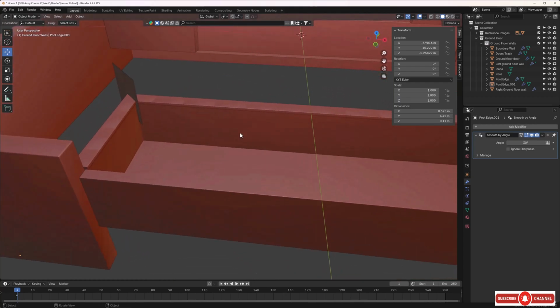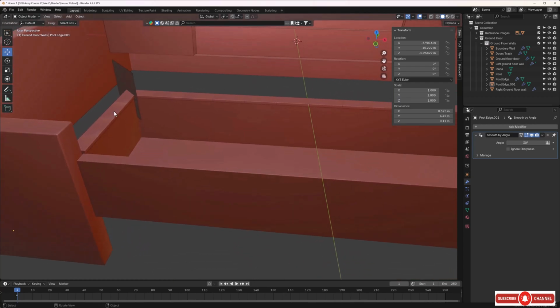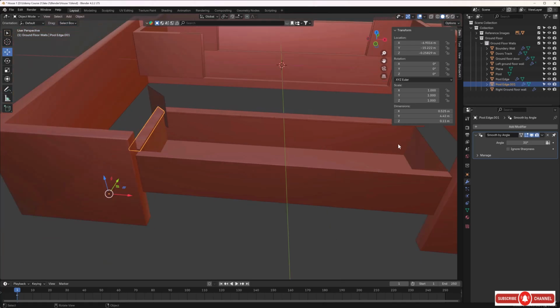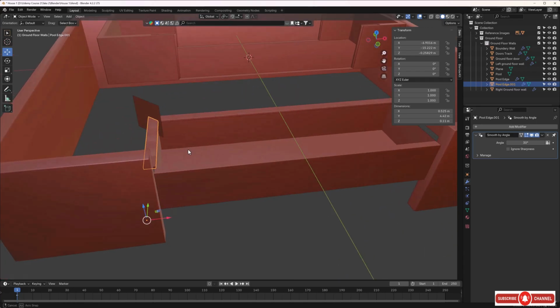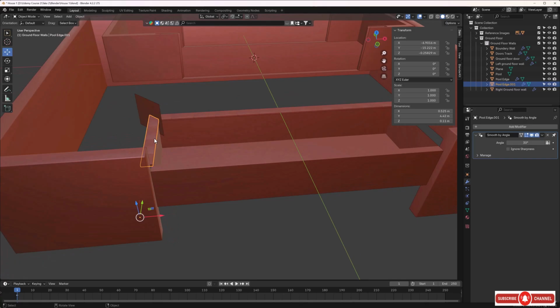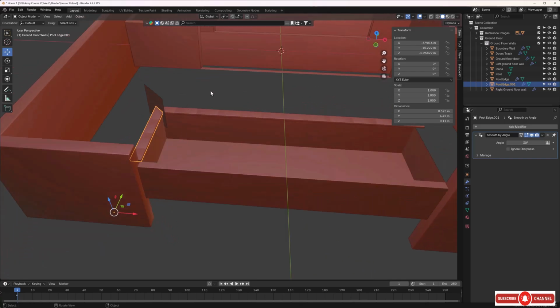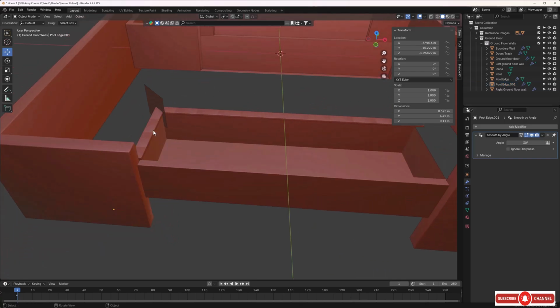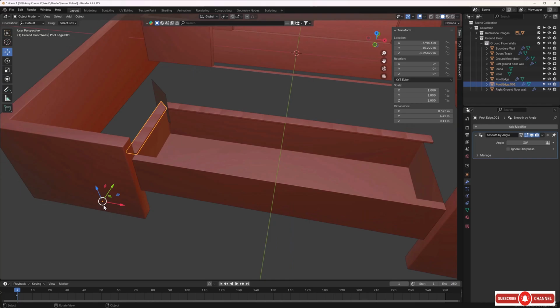So, because now we have a face on this, the opposite side of this is open. We have one face, so we can't just bring a duplicate over and flip it anymore, because it'll be incorrect. So we actually need to mirror this piece. So I need to show you how to mirror it. What we need to do is bring the pivot point for this object to the center of the swimming pool. And the pivot point right now is way over here, so that's not right for us. So let's work on this.